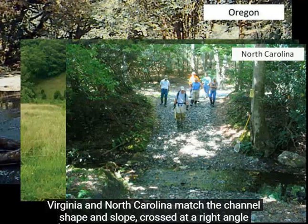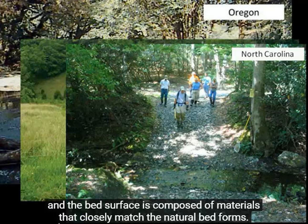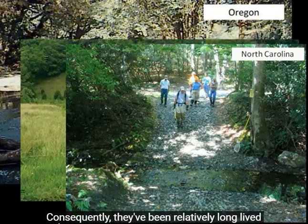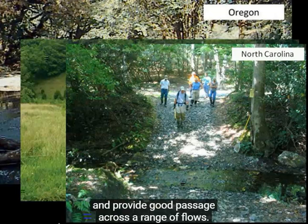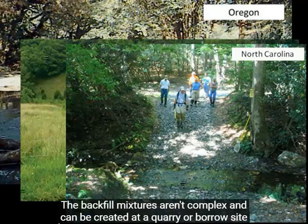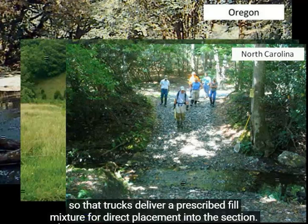and North Carolina match the channel shape and slope, cross at a right angle, and the bed surface is composed of materials that closely match the natural bed forms. Consequently, they've been relatively long-lived and provide good passage across a range of flows. The backfill mixtures aren't complex and can be created at a quarry or borrow site so that trucks deliver a prescribed fill mixture for direct placement into the section.